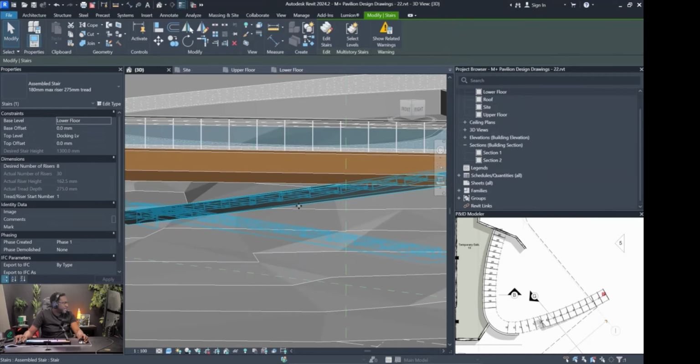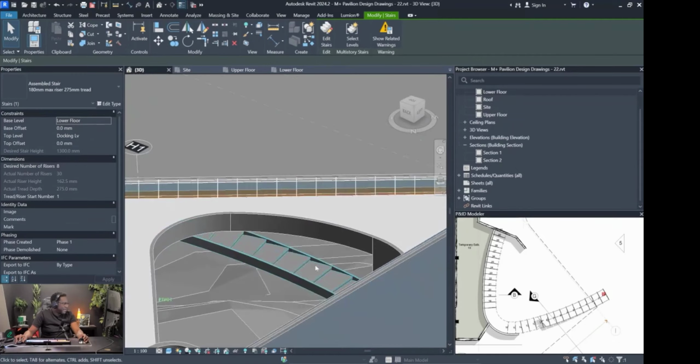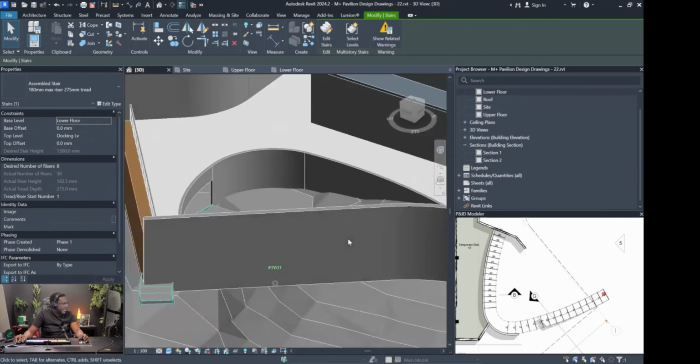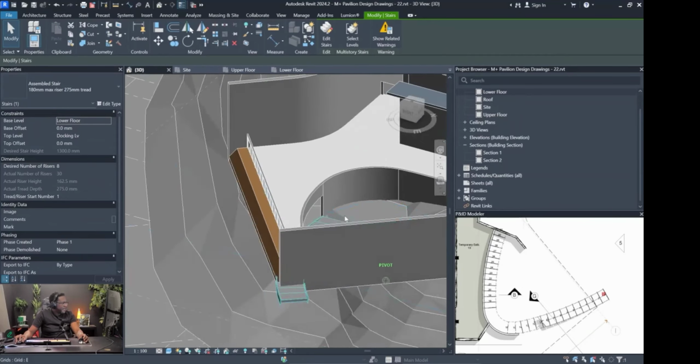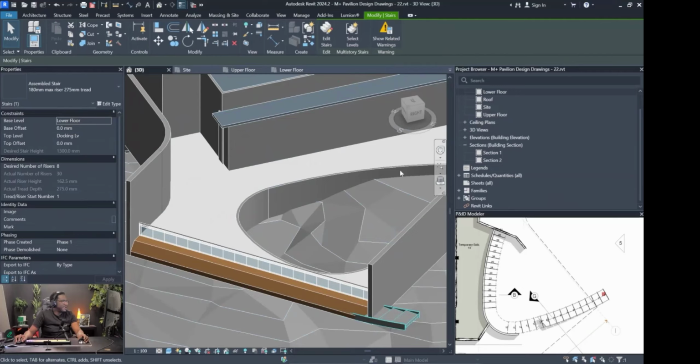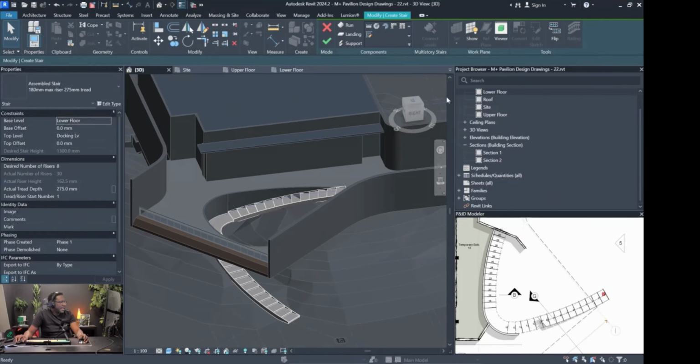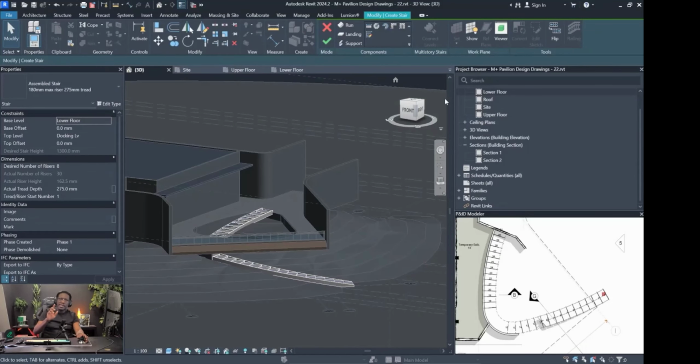We could also try the timber stairs, and now you can see that the stairs look completely different because it now has stringers at the sides. So these are different types of stairs. With this new type of stairs, if I go to edit stair and try to flip it, it does work. So what does this tell us? This tells us that our model of the stair is fine, but in the monolithic stair there is some setting that causes an error when you flip it.